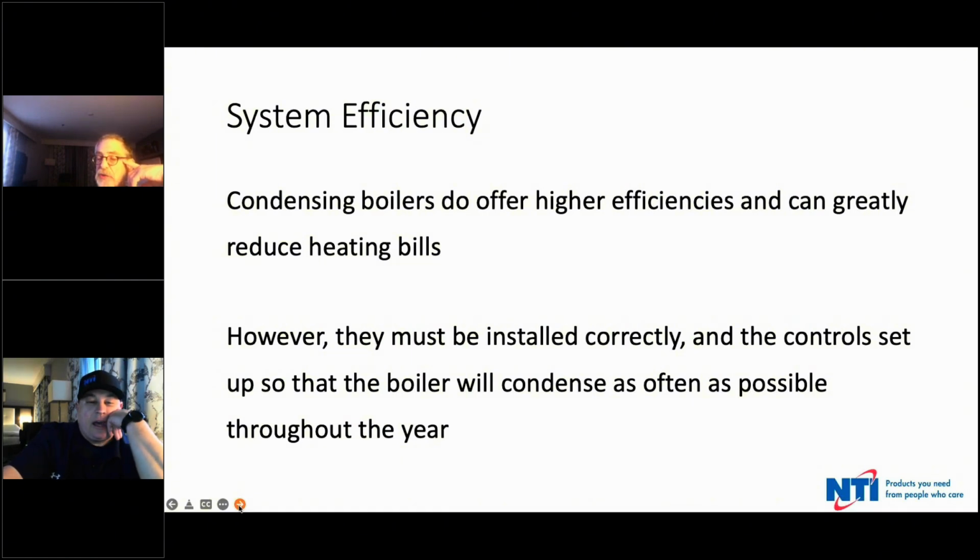Yep, that's right. You know, in other words, at 180, let's say, the average residential baseboard gives you, I think, roughly 550 BTUs a foot. But at 140, 580. And the other thing I want to talk about, and it's a little bit dangerous thinking that you're always going to get 580, because you get 580 out of the first foot of it.